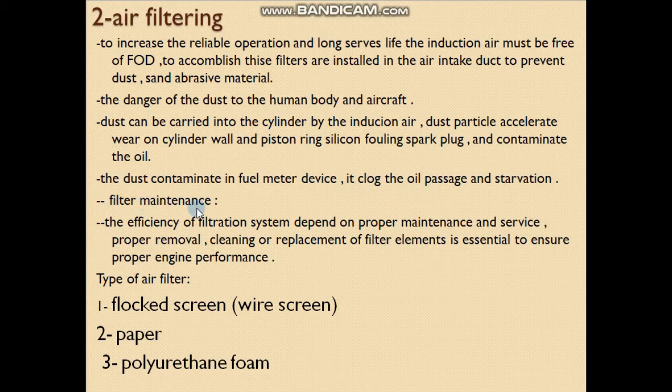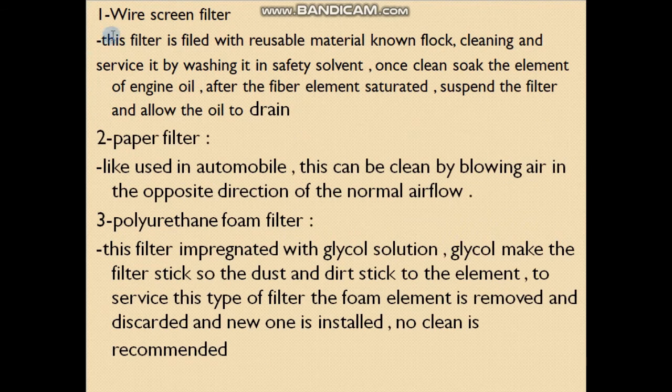Filter maintenance. The efficiency of the filtration system depends on proper maintenance and service. Proper removal, cleaning, or replacement of filter elements is essential to ensure proper engine performance. The types of air filter are the wire screen, paper filter, and polyurethane foam. We will start with the first one, the wire screen filter.